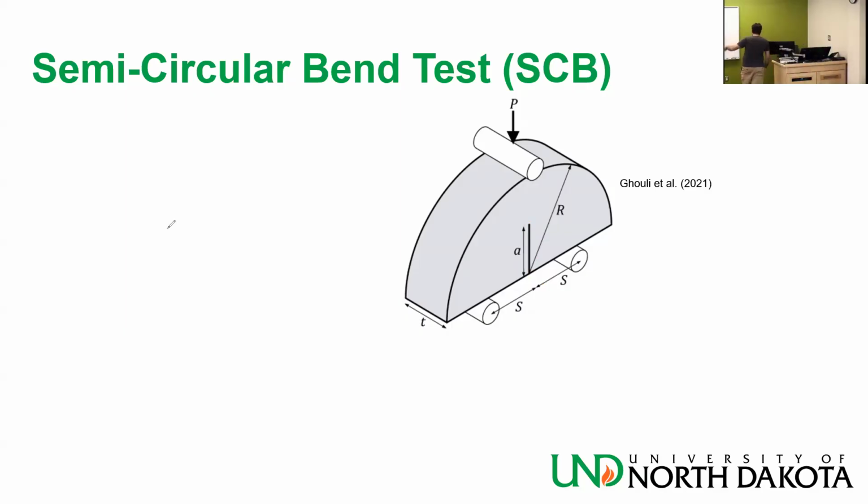We make this experiment on something called the true triaxial test, or normal triaxial test. So nothing fancy about it. There is a plate that moves slowly upwards. So you put the sample there, you make sure it touches the top and the bottom, and then slowly the bottom plate moves up. Slowly, slowly, slowly, and then it cracks.